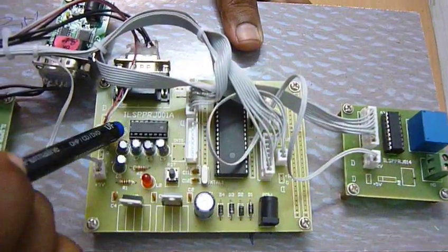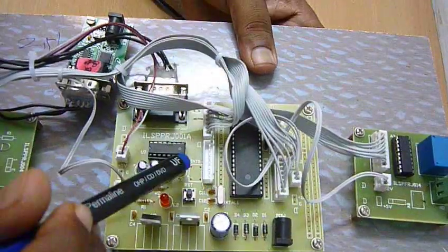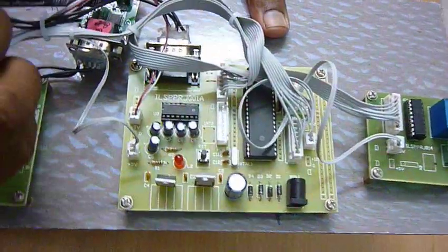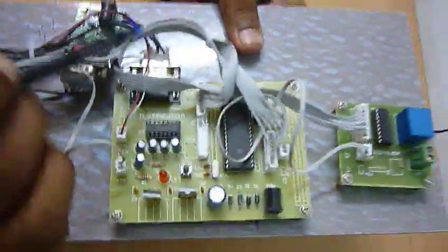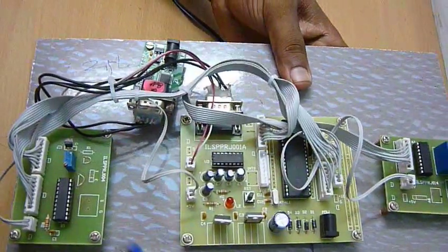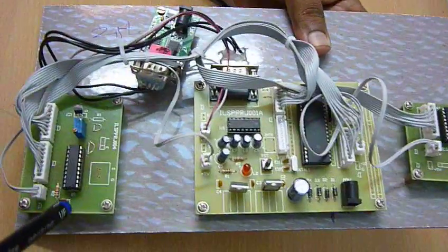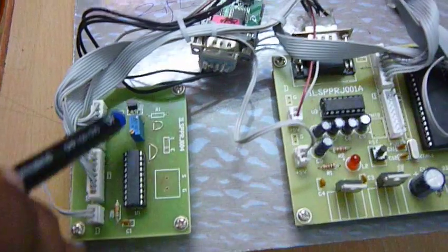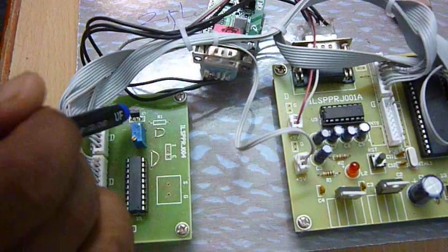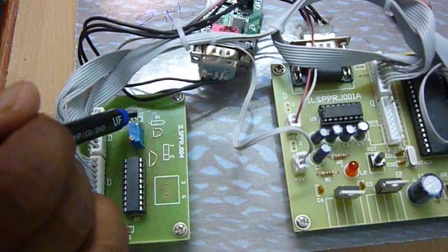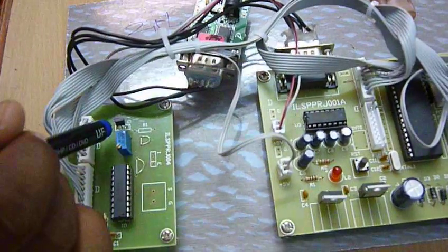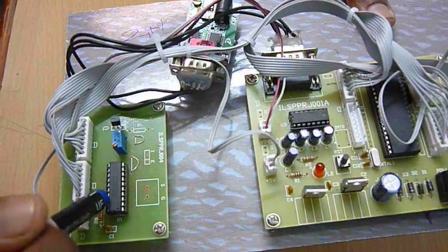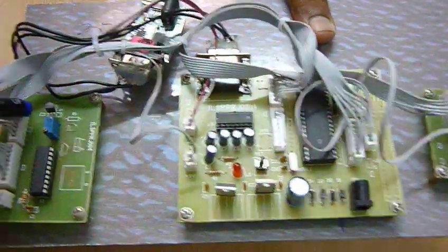This is called a MAX 232 IC. This MAX 232 IC along with these 4 capacitors is used to interface this particular microcontroller to the ZIGBEE transmitter via RS-232 interface. This is an ADC board. The purpose of the ADC board is to convert the analog information coming from the temperature sensor into digital. This is the temperature sensor. We are using LM35 temperature sensor for measuring the current temperature. This ADC0804 is controlled by this microcontroller using a couple of parallel ports.